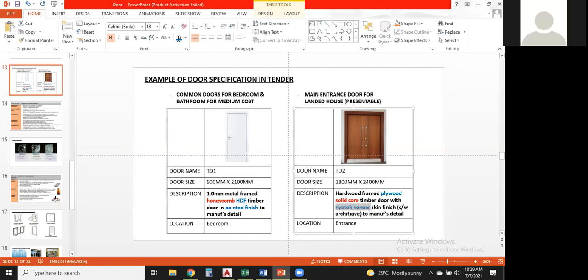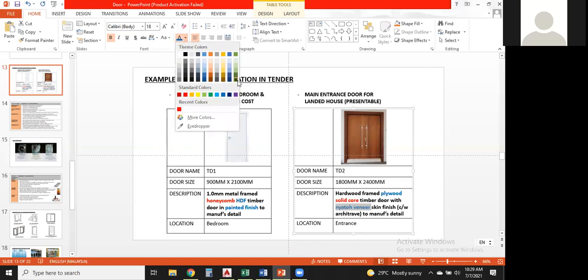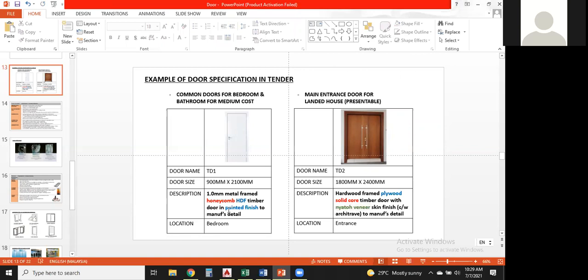So our QS came back asking, why do you have a metal frame, then suddenly you have architrave? Where is your architrave? So just to take note, all the drafters and assistants, because sometimes we keep using the same title block and templates, and we never read the notes originally put in the title blocks. So sometimes it does not tally with our description, and this will cause confusion to the QS and to the contractors.